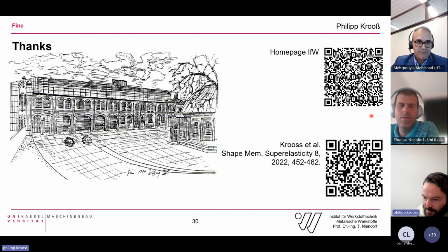Also, atom probe or other techniques are usable, but TEM is, I think, the most common technique to show the precipitates, also the size and the morphology and the coherency and every particle property that is important. I hope that answers the question.